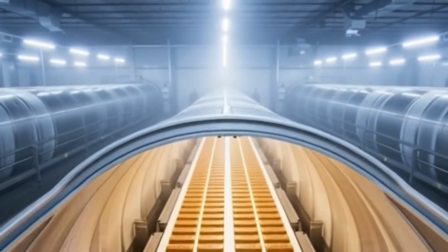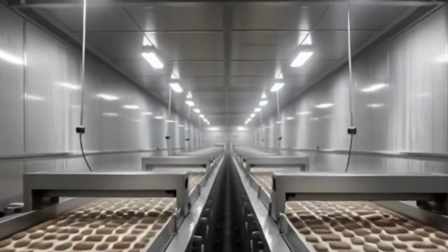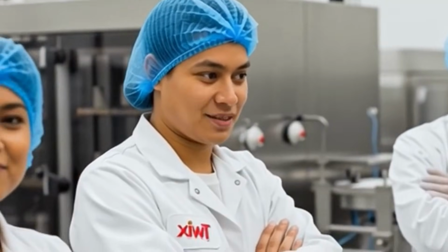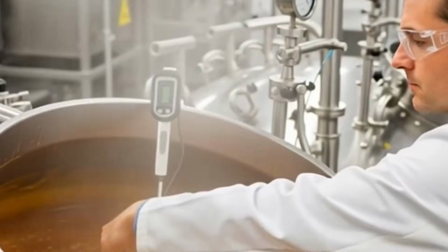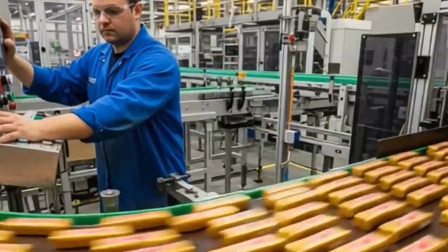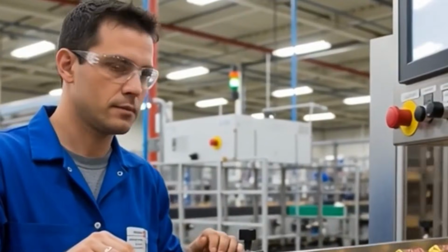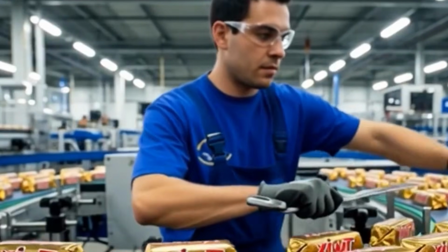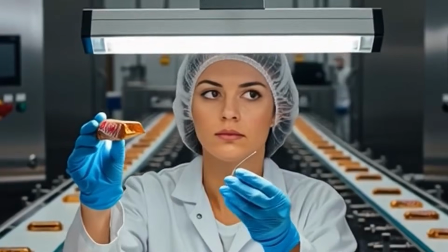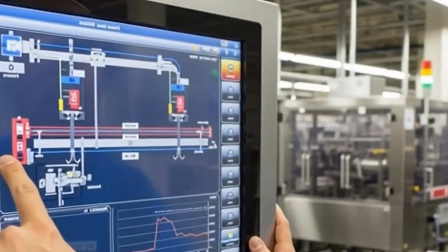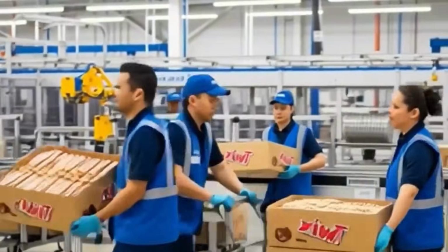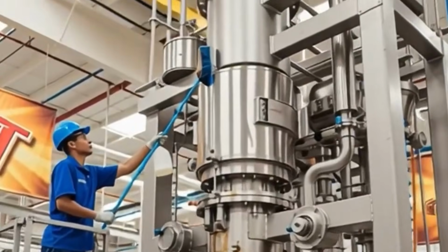In the rotary molding station, the dough is formed into uniform, rectangular shortbread fingers. The molder consists of a rotating drum engraved with bar-shaped cavities and a compression roller. Dough is pressed into these cavities as the drum rotates over a steel forming plate. Excess dough is scraped off by a doctor blade and recirculated back into the feed system. The molded dough pieces drop onto a perforated baking belt made of food-grade stainless steel mesh.